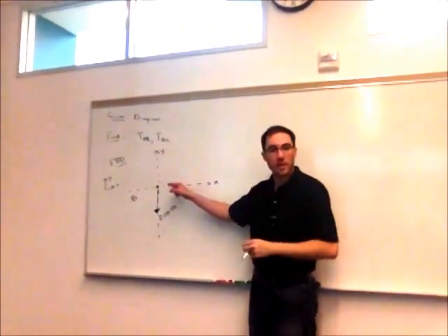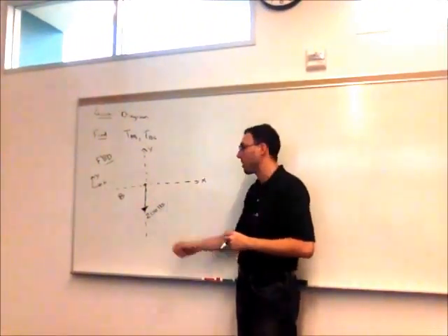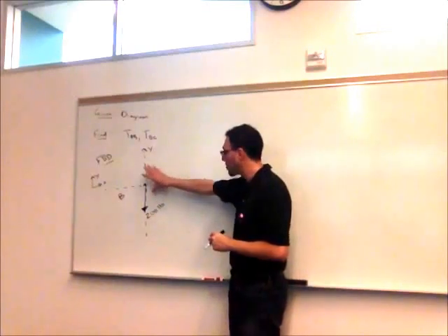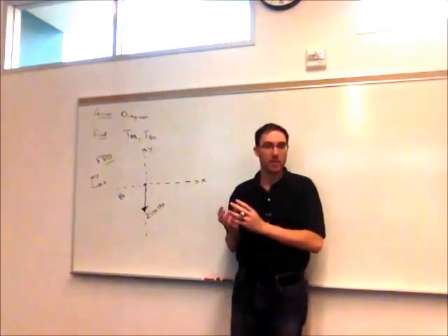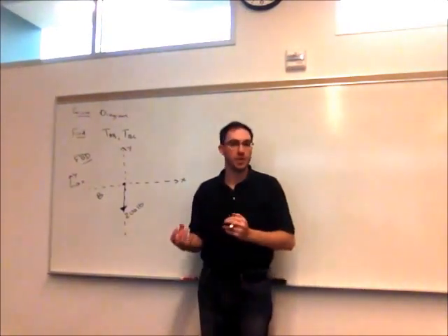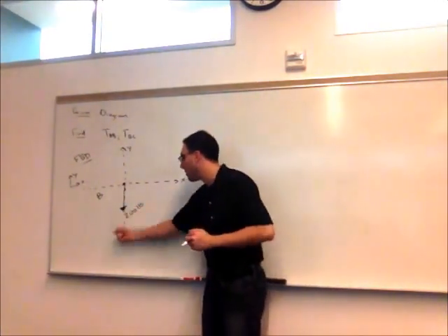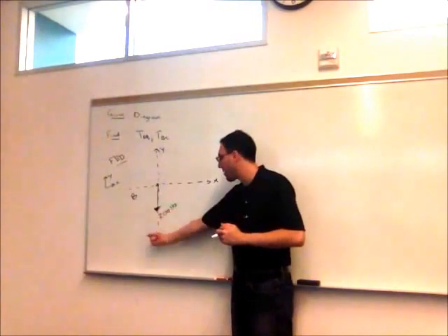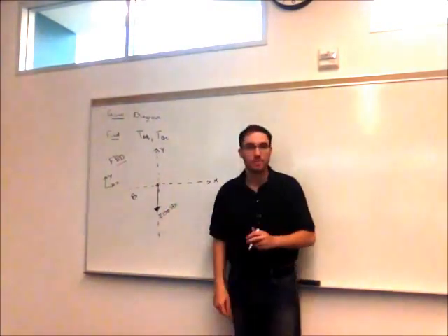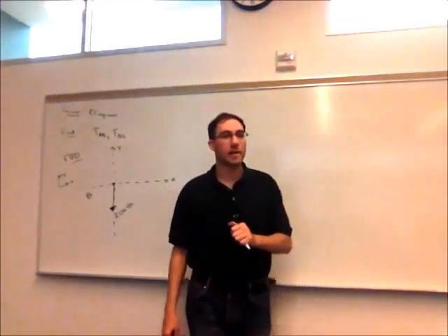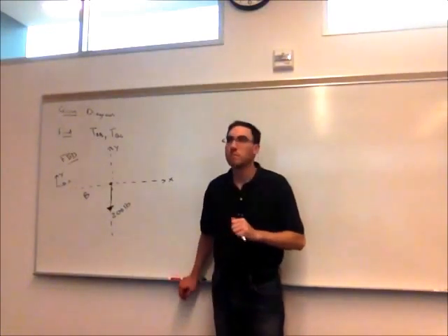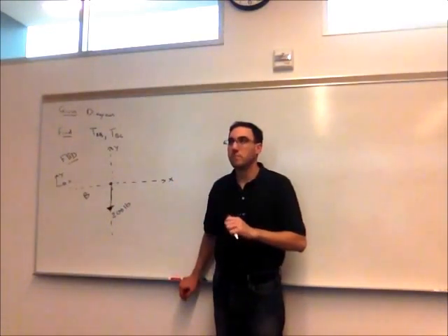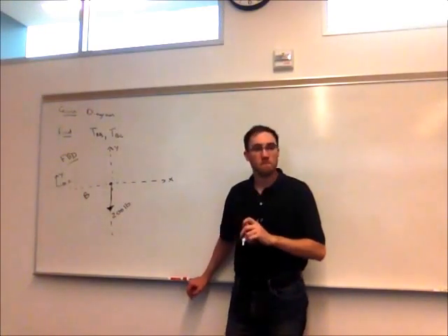Right, so the rope is not in the picture, but the force that the rope exerts on B is on the picture. We're only drawing what all of these things do to the object, not what the object does to these other things. So this force alone pulls our object down. Right, what other forces are acting on our object? You have the tension from BA and BC at the given degrees.